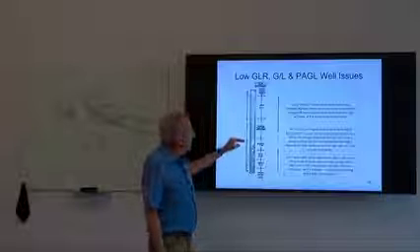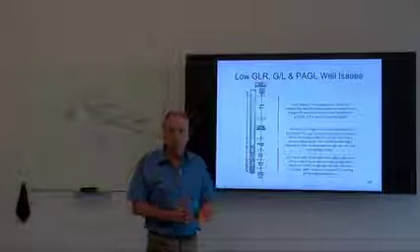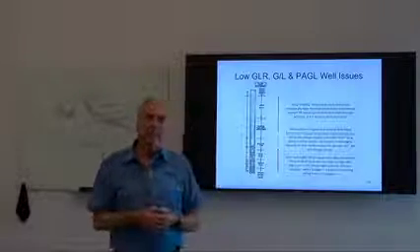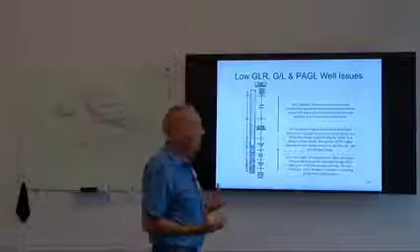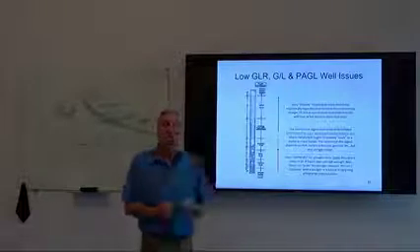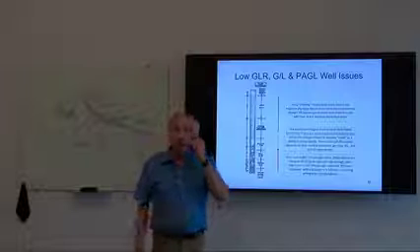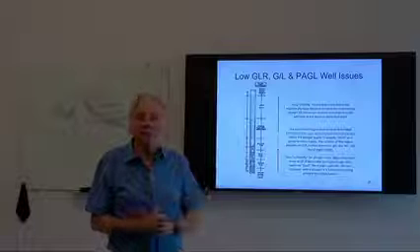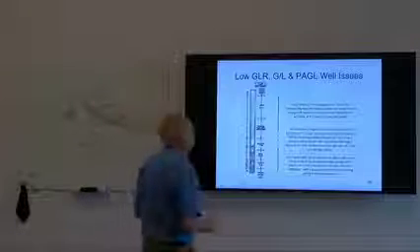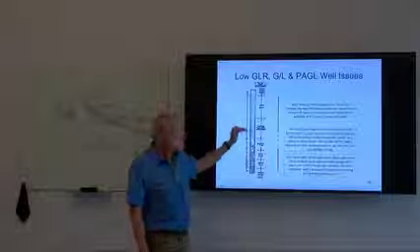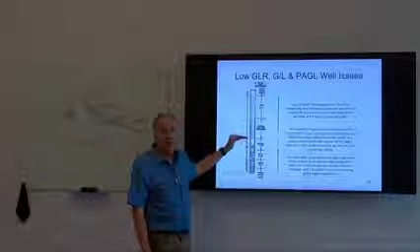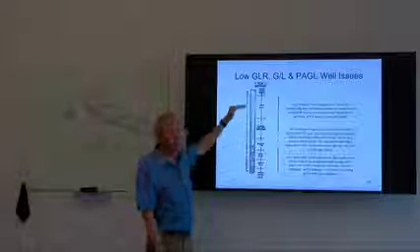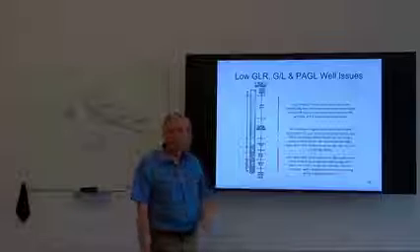So understanding these various changes in the flow regimes and just what that means from a plunger travel environment, a pumping environment, it's very important to understand that we can't just say, well, let's land our bottom hole spring assembly at the lowest point in the tubing and assume that we can pump from there. Sometimes we actually have to set our tubing stop or a collar stop for our bottom hole assembly at some intermediate point to be able to lift effectively.